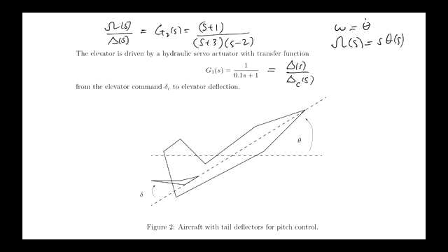Our interface to this control surface is through a hydraulic servo, okay, which itself has dynamics. It has this transfer function here. All right. So the controller that we're going to look at designing goes from this command of the hydraulic servo, which gets converted into the angle of this control surface via the transfer function 1 on 0.1s plus 1, right?